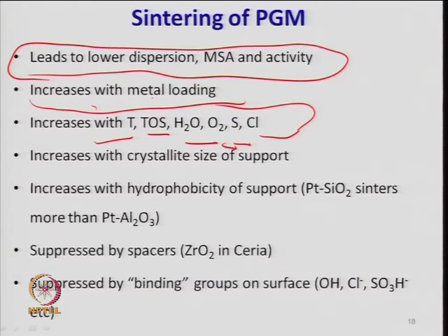Water may be a problem, so do sufficient aging or drying before calcination. The same with the oxygen environment, which should be controlled. Sulfur and chloride should be avoided, as these are certain precursors which may affect the performance.